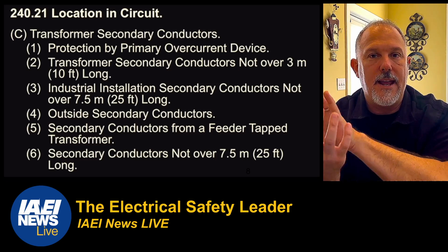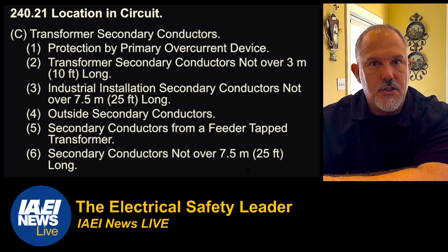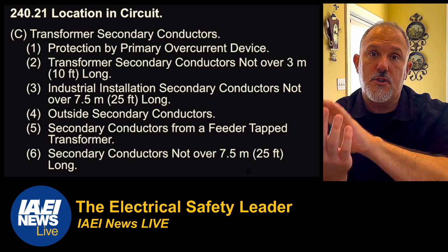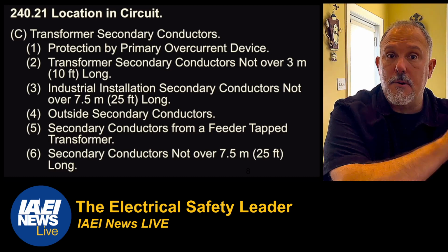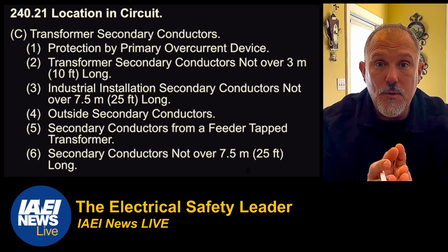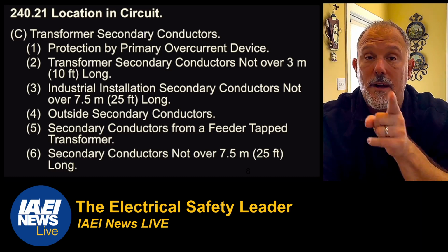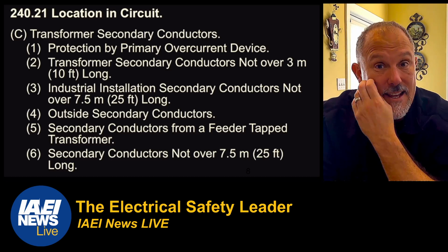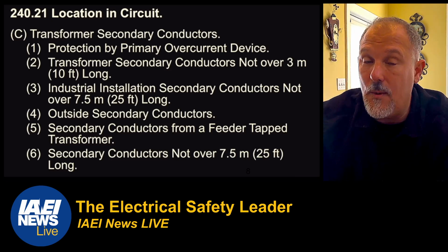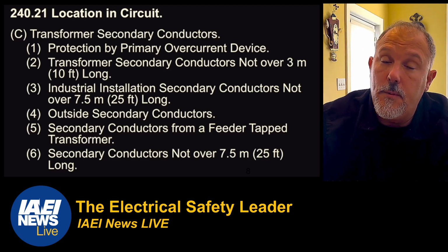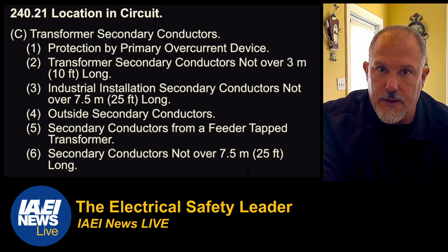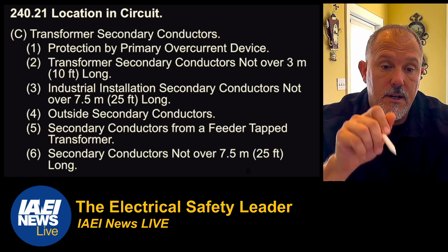So what you're doing is you're transposing. You're taking the secondary amp rating of the conductor on the secondary of the transformer, multiplying that by the secondary voltage, dividing that by the primary voltage. So you're transposing the ampacity of that conductor to the primary, and then comparing that with the primary overcurrent protective device. And that's only for two types of transformers, two types of systems. One's a single phase, 2-wire, and the other is a delta-delta. So for those cases where you have delta-Y grounded transformers, which is probably the bulk of what we deal with, you're not going to get away with establishing the primary overcurrent protective device protecting the secondary conductor because of that rule,